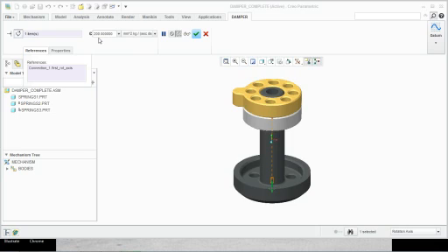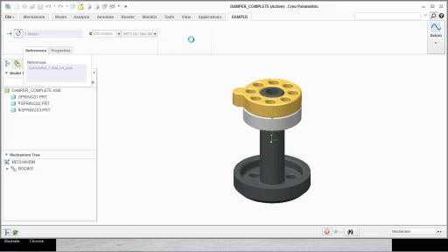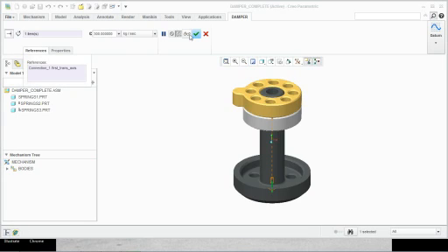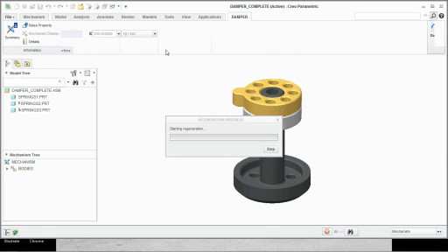So that's where the C is going to be used. You have a rotational damper, and then you also have an extensional damper. You can see we use the translational axis right here as a reference for C. So when you run this analysis, you can see that's where it stops, because the damper takes care of all the other motions.